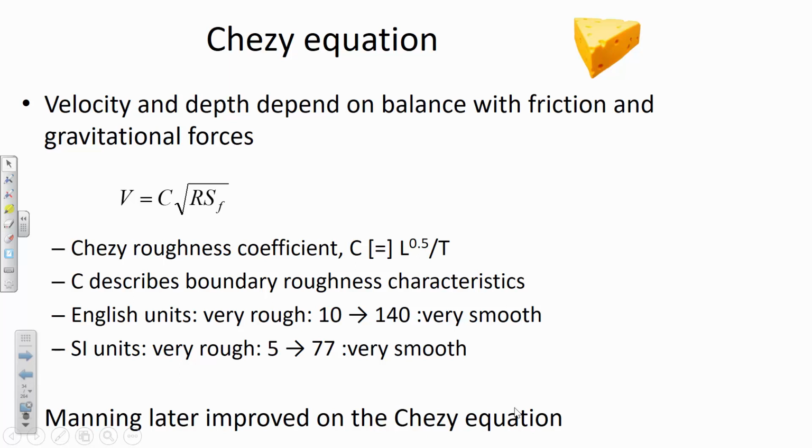So just a little bit of a history lesson that there are simple and older equations to estimate empirical friction effects, and the Chezy is one of them. Now, in your book on page 201, there's an equation that tells you how to relate the friction factor and the Chezy equation. And so, in very rare cases, you may find infrastructure still in place that was designed when the Chezy equation was utilized.